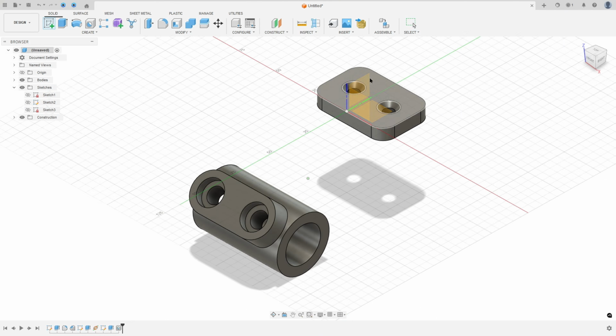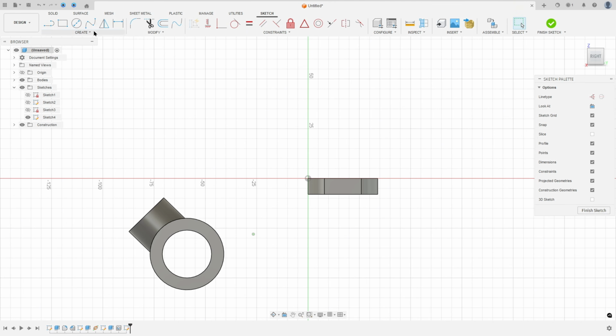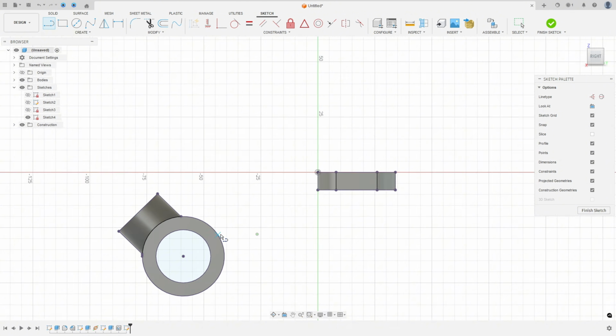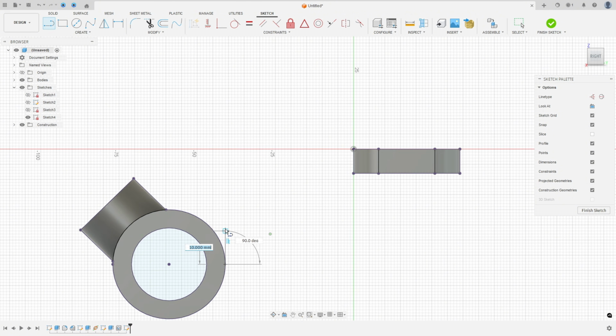So go to create a sketch, select the right plane, go to create, select project, include project, the selection filter, select the bodies, select this tool body here and press OK. Now select a line, make a line here, an arc and another line. Go to constraints, make this arc tangent with both lines and make this line horizontal, and select this point here and this point here, and go to sketch dimension.